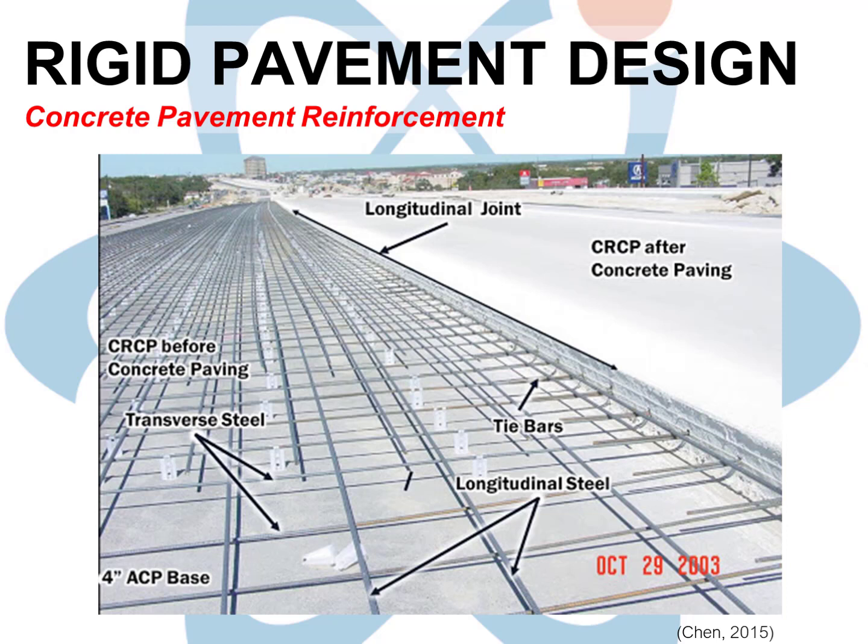CRCP means continuously reinforced concrete pavement, and it's when we install a mat of steel both lengthwise and crosswise in a pavement. This is a great way to make a pavement really strong and capable of resisting tremendous loads. It's also very expensive, and when the day comes when the pavement finally has to be demolished, it makes for a nightmare for the demolition crew, as the steel continues to perform its job of holding the concrete together.